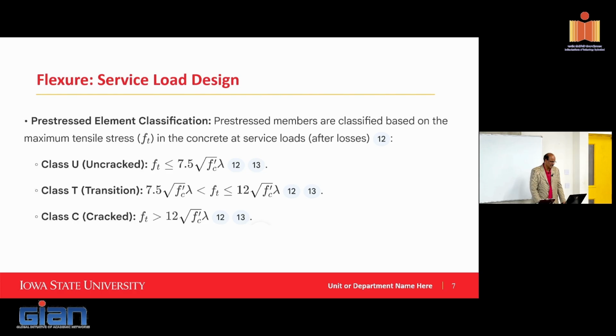The key piece here is how you would classify your member as a cracked section versus an uncracked section. They use that tension capacity to classify it. So if you're estimating displacement or deflections and things like that, cracked versus uncracked makes a big difference.